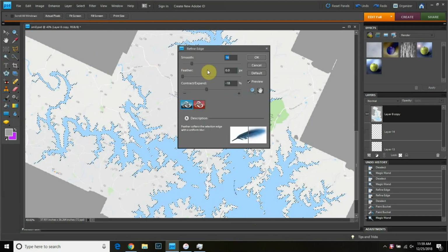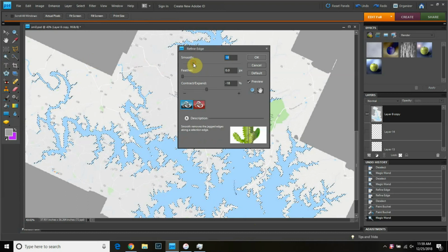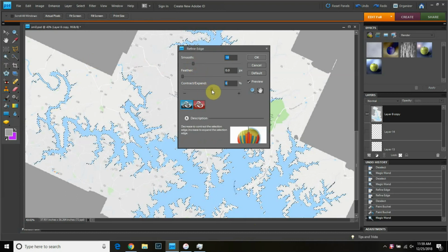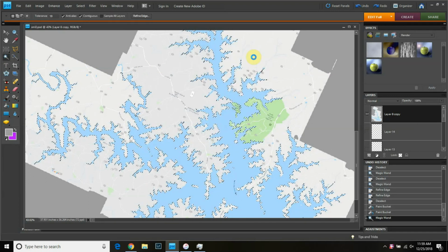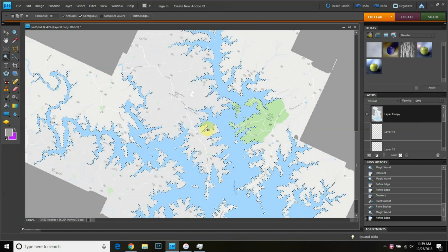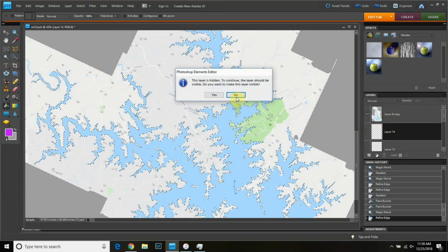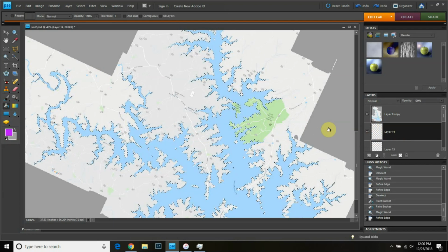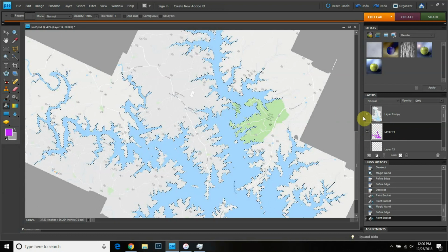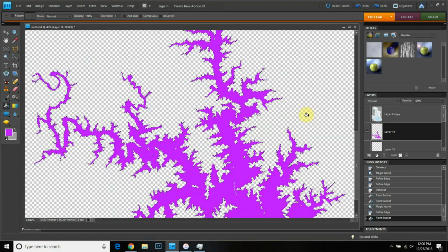From there, we put it into Photoshop. Using Photoshop, we can extract an outline and get it into a PNG or JPEG format. But the CAD program doesn't take that format. What we need to do is take that outline and put it into Inkscape. I didn't picture that here. Inkscape will take it, convert it to a bitmap, and then extract the outline. And that outline you can use to make an SVG. The SVG format, scalable vector graphics, is what goes into our CAD program.